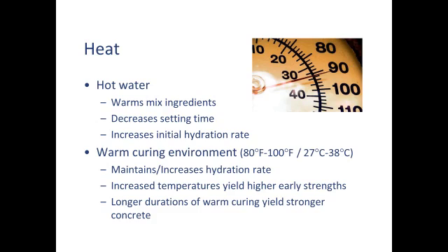And when you warm cure your concrete, you're only gaining strength at that temperature while the concrete's warm. Once it cools off, it's going to slow back down. It's kind of like driving your car. You only go fast when you push the accelerator, and there are no downhills to coast, so to speak.